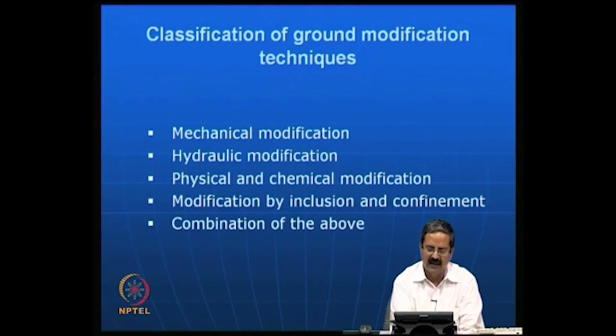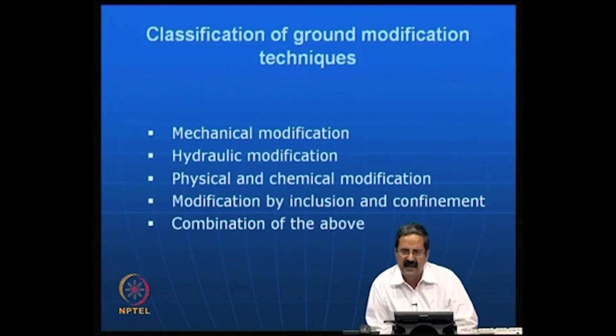So, what we do, one can physically modify, in the sense add some admixtures like sand, fly ash, or any other material like a dust material that is available, and which are inert. Actually, this sand, fly ash and all are comparatively inert compared to clay, because the clays have negatively charged surface particles on them, and when the negative charge is high, the problem is that they take a lot of water. So, if you can modify the physical state by some additives, then it is nice.